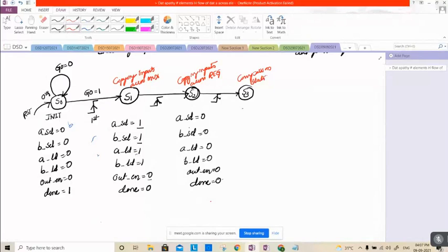You may ask your question at the end of the class after the complete analysis of the example. So why S2 and S3? Two are not needed, sir, only S2 is sufficient. A comparator is not a sequential element, so the comparator has no clock signal. So why can't it compare the values in S2 state itself? Yes, it can compare in S2 state also. There is no necessity for the S3 state, but we'll see a little later why it is placed here. The comparison is done.